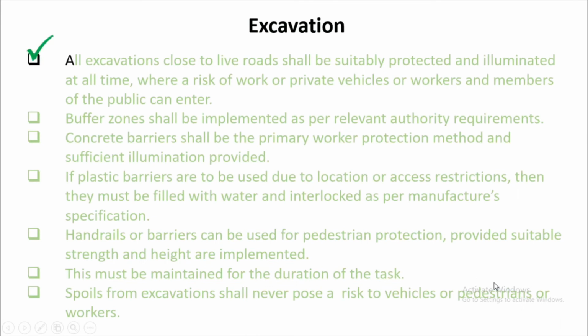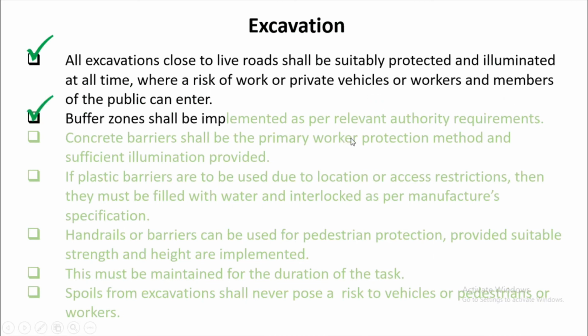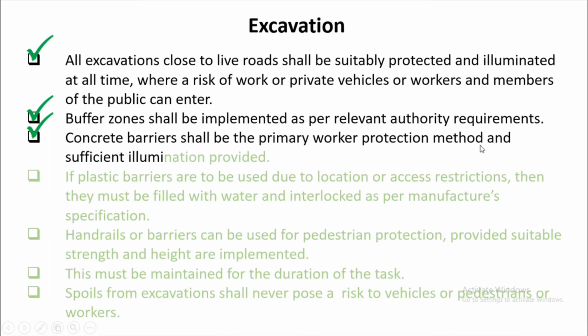For excavation in traffic areas, all excavation close to live roads shall be suitably protected and illuminated at all times, where there is a risk of work or private vehicles, workers, and members of the public entering. Buffer zones shall be implemented as per relevant authority requirements. Concrete barriers shall be the primary worker protection method, and sufficient illumination shall be provided.